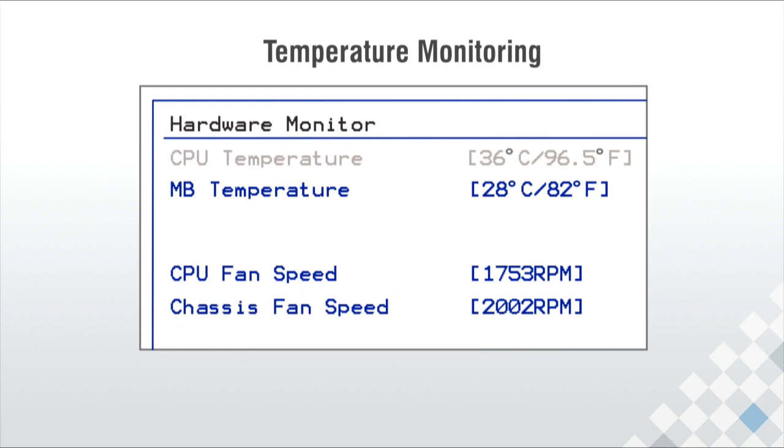Unlike using the BIOS or UEFI utility, these tools allow you to dynamically monitor the temperature as the system is being used. Most motherboards include a thermal shutdown feature. If the system gets too hot, the thermal shutdown feature immediately shuts the system down to prevent permanent damage. However, it usually doesn't do so cleanly, and there is a risk of data corruption as a result.